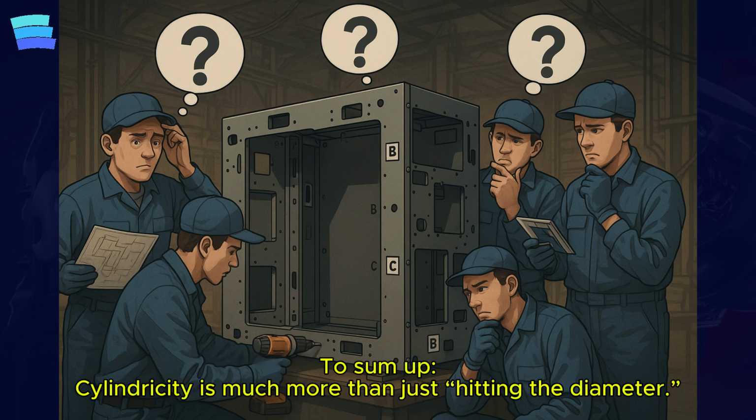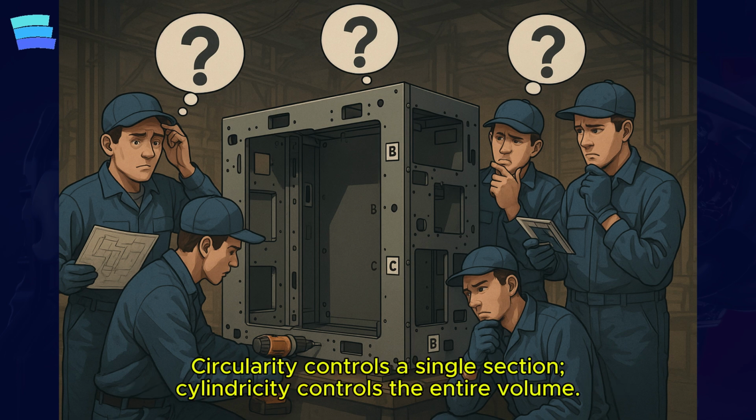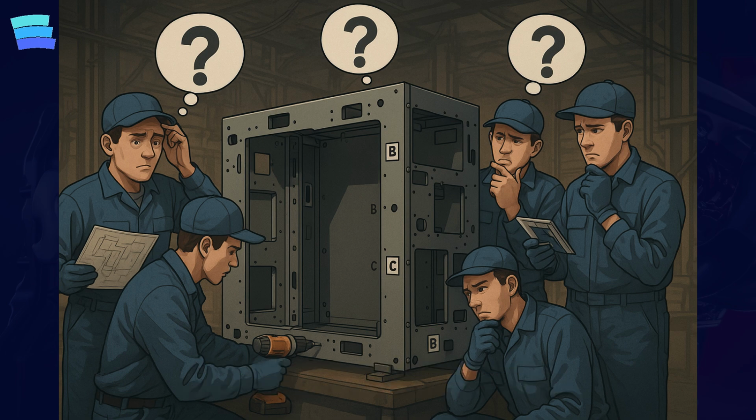To sum up, cylindricity is much more than just hitting the diameter. It defines how the form behaves with respect to the axis along the entire surface. Circularity controls a single section, cylindricity controls the entire volume.